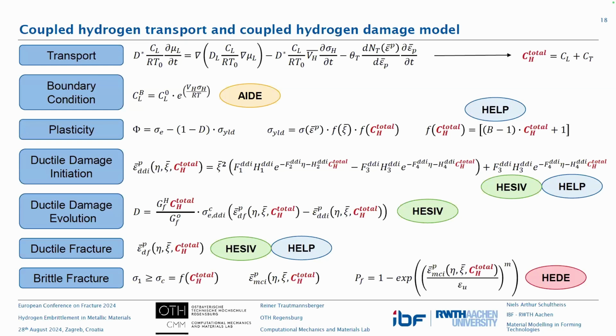And the idea is that the local critical cleavage fracture stress is also a function of local hydrogen concentration, lowering this critical value, and thus incorporating also the ideas of the HEDE mechanism. And the beauty of this model is that it would, to some degree, dynamically incorporate all the effects at the same time because they're solved on an element basis. That's really the key aspect of this model.